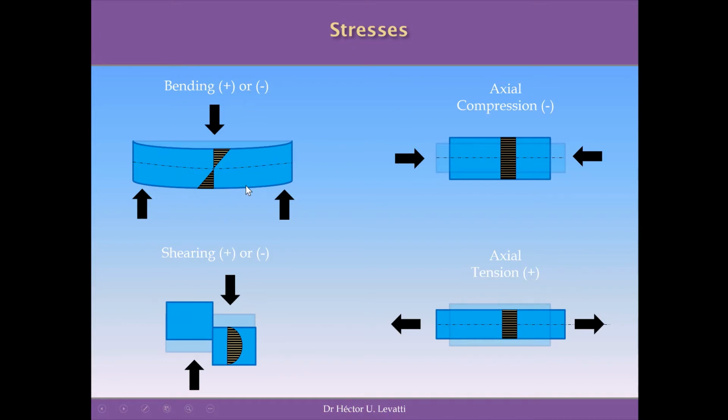As you see as well, the bending has different signs, and we say that the positive sign corresponds to tension, and in this particular example the tension is produced under the neutral axis because there is elongation of these fibers here, as you can see. And this elongation will produce a tensile stress, and the maximum will be at the bottom. On top, because there is a contraction of the fibers, you will have a linear distribution of compressive stresses, and the maximum will be on top of the cross section.